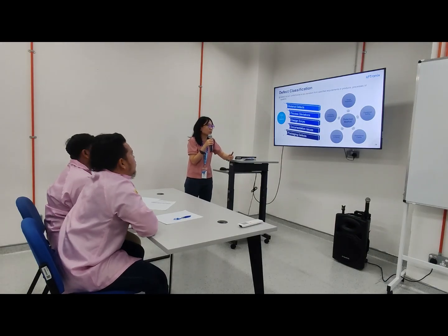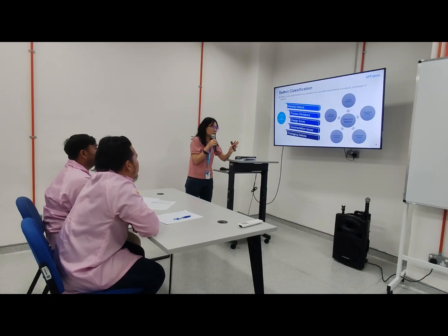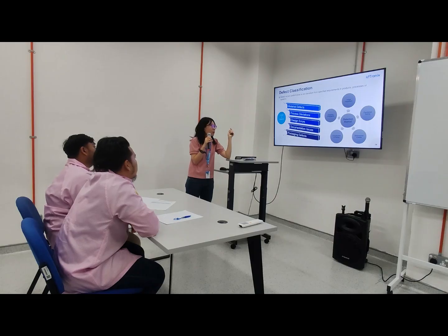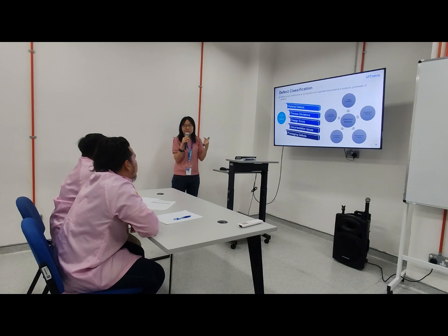For example, we use visual inspection, a visual check whether there is any appearance issue or not. And functional check, a functional test to verify whether the product can function or not. We also have dimensional check, where we measure using calipers and check flatness, for example. Environmental testing is normally for the material, where we have RoHS compliance. Previously, all the material will have the environmental check. Then the detection method of customer complaint is the last resort.